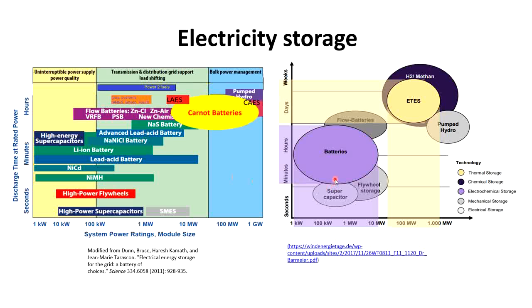We can see that also here on the right side, the very left and bottom part: supercapacitors, then eventually some flywheels, then the area of solid state batteries and flow batteries, and then for the very highest power outputs and also the largest discharge durations are methods such as pumped hydro, eventually power to fuels, as we have here hydrogen or methane.